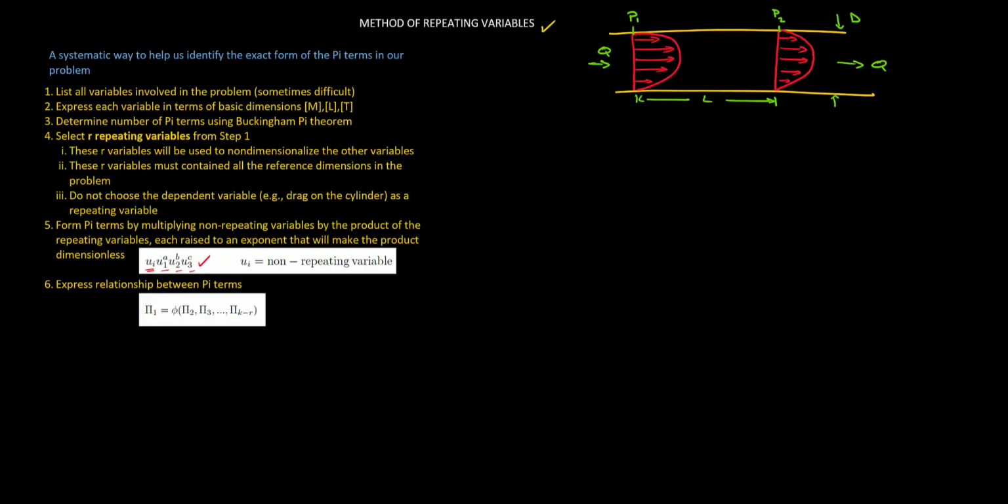So what we want to do is set up an experiment to determine the dependence of the pressure drop on the variables of importance in the flow. Okay, so we want to find the pressure drop, delta P, is equal to a function of something, right? So this is our experiment. So let's think through what flow parameters could affect the pressure drop along a pipe.